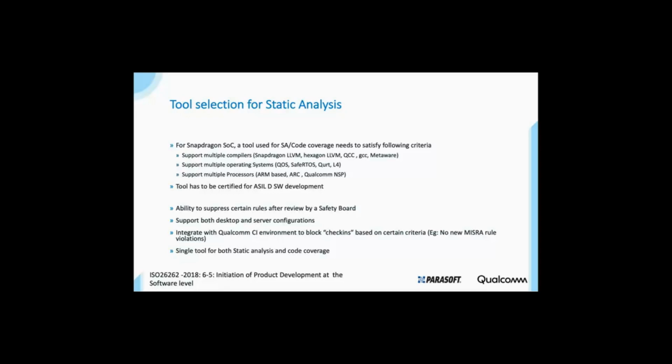But when we were looking for a tool, we had a few criteria. One is, as I said, we had a complex SOC, so the tool has to support multiple compilers, multiple operating systems, and multiple processors. Typically for static analysis, we found a lot of tools scale well, but when it comes to code coverage, where the instrumented code has to run on a certain processor, a lot of tools don't scale. So we were looking for a tool which would satisfy all these various environments. And then we wanted to make sure that the tool is certified for ASIL D software development.